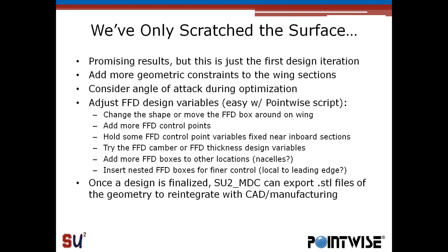And then lastly, once the designer is happy with the final result, inside of SU2 MDC, one of our tools, you can export an STL file of the geometry and reintegrate that with your CAD or manufacturing process. So with that, that's SU2, and that's how we do shape design in SU2. Thank you for joining today, and I'll turn it back to Travis.